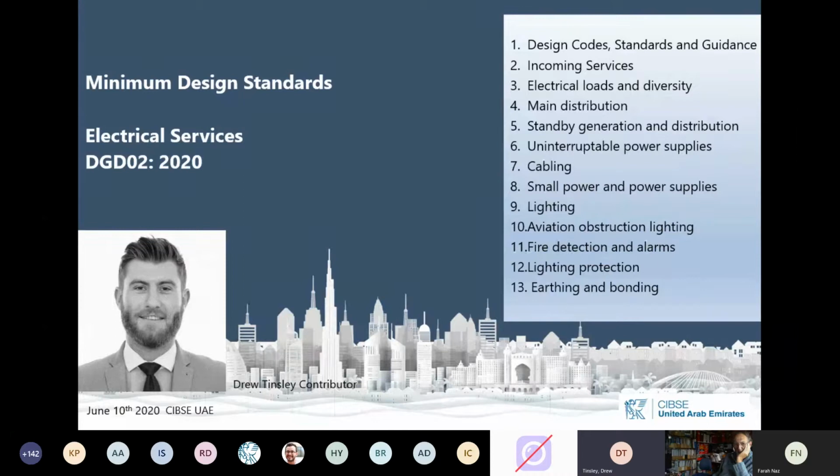Harmonic suppression is covered, as well as motor starters and the mandatory requirements for DEWA in terms of metering, which is quite important in this region, given the mixed-use nature of buildings, large buildings that are landlord driven but with tenant supplies also. Section 5 covers standby generation in a generic sense. It defines the key principles for standby generation in terms of fire and life safety, how fire and life safety needs to be covered, critical systems, and generally anything that requires business continuity.